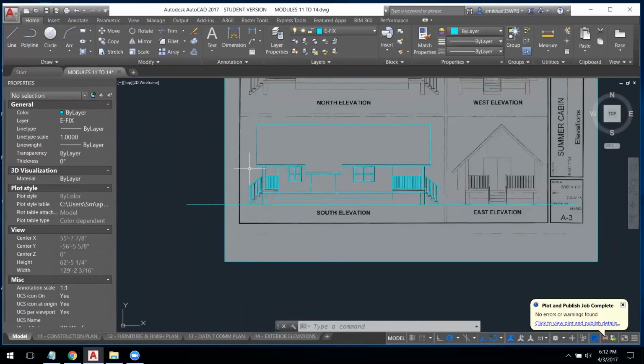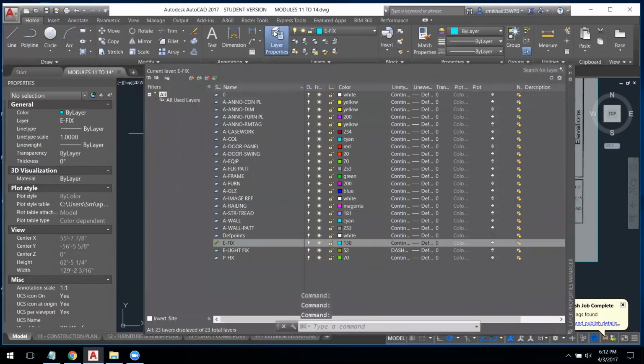One standard that you will see often is that we create elevation, elev layers, one that's called dark, medium, and light. And we basically use 3 line weights throughout the entire elevation, in addition to the ground plane. We don't use a wall, a window, a door. Some offices do, but by creating this light, medium, and dark, it creates more flexibility.